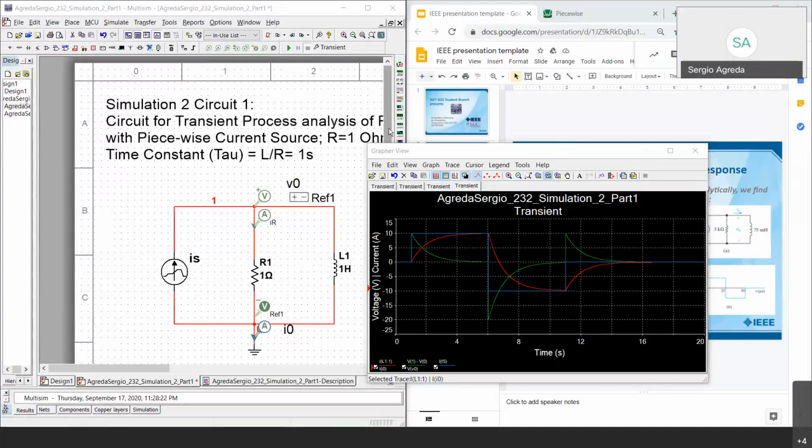That's mainly how I like to set up your circuit, or just the first part of what the simulation assignment will ask for. Then he usually likes to ask you to graphically calculate or estimate the time constant. This is where it's important to get used to using the graph viewer of Multisim, especially once you get later into your other simulations.